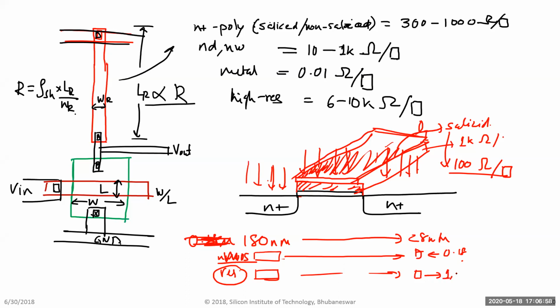They will say, no, you have to keep it 1 micron because you're doing long resistors and we can't guarantee it. So the short answer is that resistors don't scale that much. But yes, there are some effects. Resistors and capacitors, especially in a digital technology, are almost a parasitic effect.